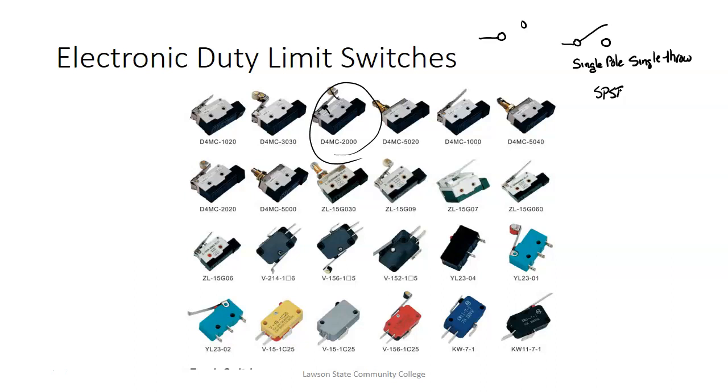Most light switches, if you've got a two position, where you can turn the light off or on from multiple places, those are single pole double throws. And I can show you all the circuit. But if you go out to Lowe's and you pick up a set of regular light switches, odds are you're going to see that SPST on there somewhere, which means they're single pole, single throws.